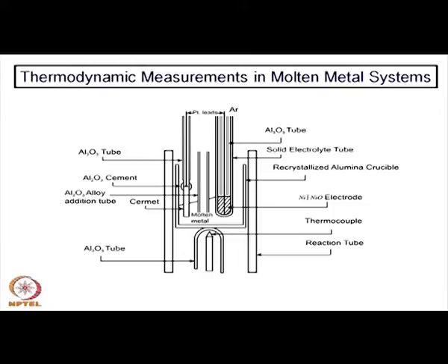So, in automatic control of ceramic kilns, these sensors become quite handy, and most of the modern furnaces are fitted with this kind of sensor, so that the fuel combustion process can be controlled quite efficiently. So, that is another area where, besides automobiles, there is a huge application of zirconia oxygen sensors in combustion control of industrial furnaces.